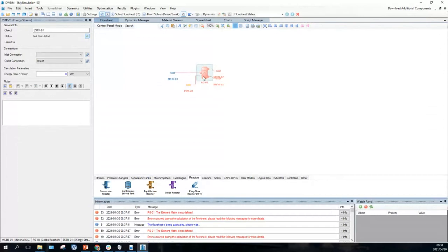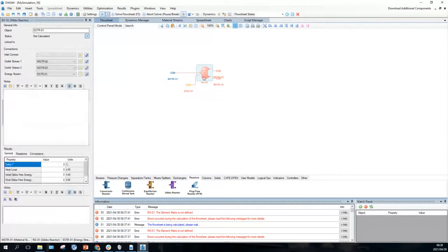Because the water gas shift reaction, you'll probably execute in a different reactor to the methanol synthesis reactor. In Fischer-Tropsch, the iron catalyst that Sasol uses is very strong on supporting the water gas shift reaction, and for that reason it makes CO2 instead of water with the Fischer-Tropsch reaction at Sasol.